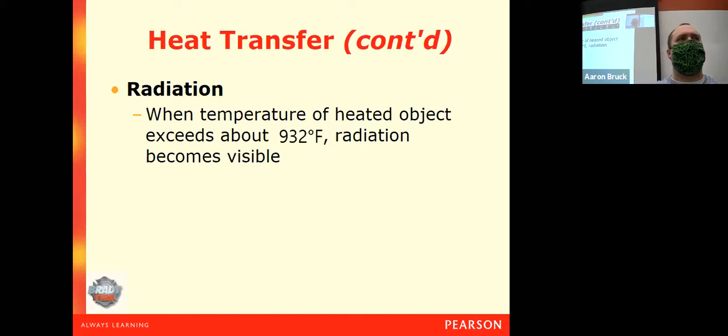So we tend to think of it most as this kind of side-to-side heat radiation, because the bottom of a container is going to be touching something else and heat primarily via conduction. Above the container, above the hot object, we're gonna see more convection currents. We tend to think of radiation as kind of a side-to-side thing, but understand, heat radiates in all directions. It's just these other two forces tend to dominate radiation by comparison.